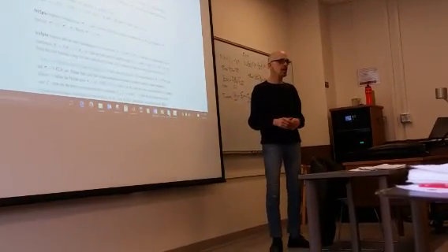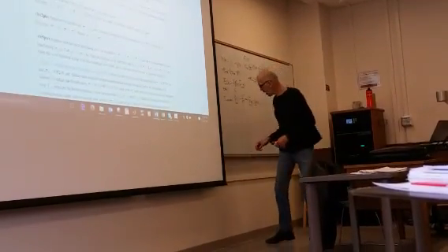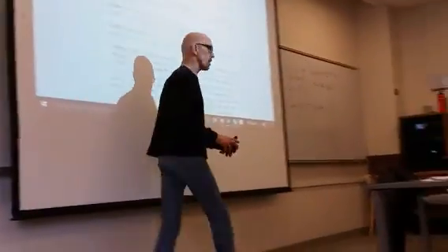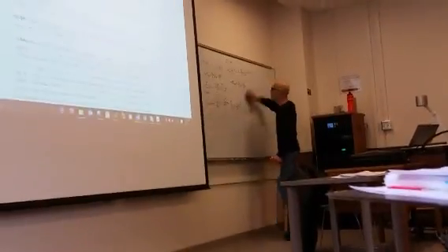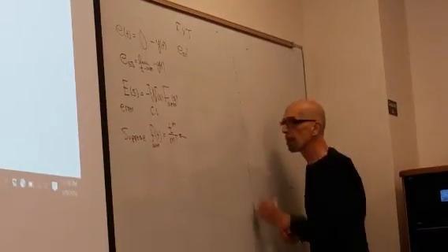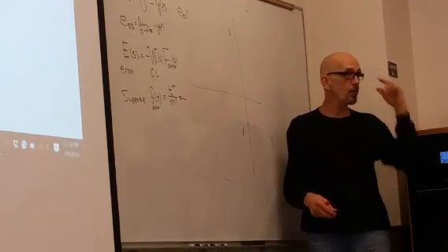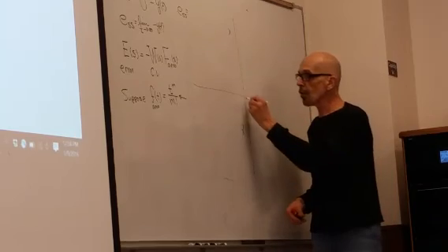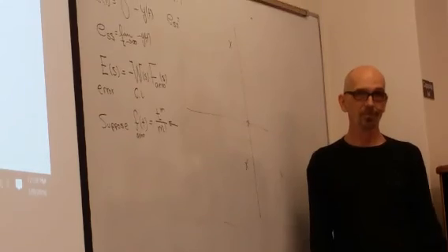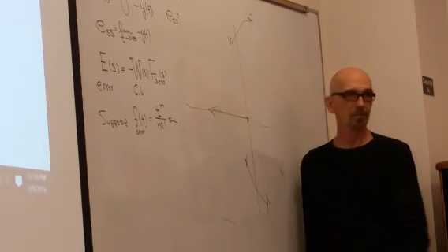It's so much easier to analyze this controller design using the root locus. So let's just, last 1 minute, sketch out the root locus. The plant has a pair of complex poles. They're very low damped poles. So the root locus looks like this. These are the plant poles, right? They're the conjugate pair from the second order system. This is the controller pole. What's the root locus? Not good.